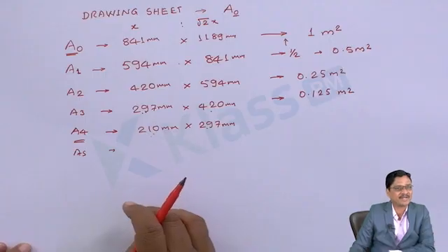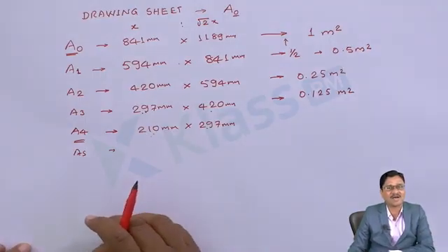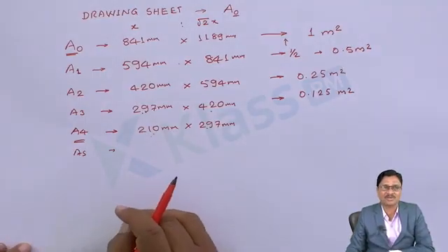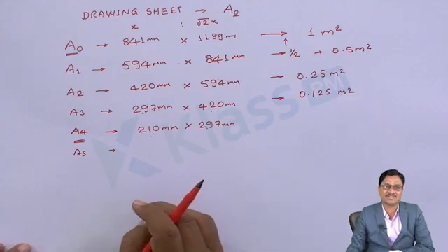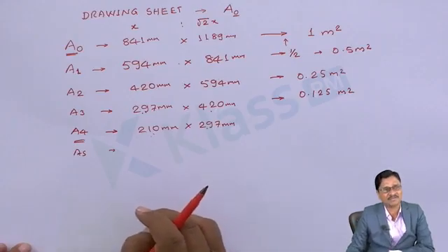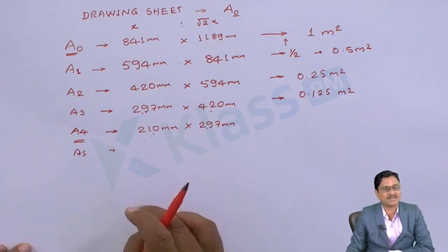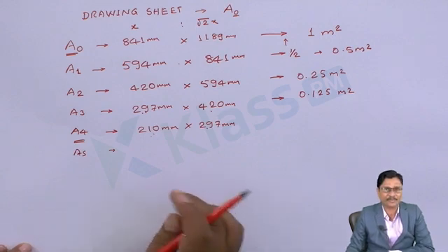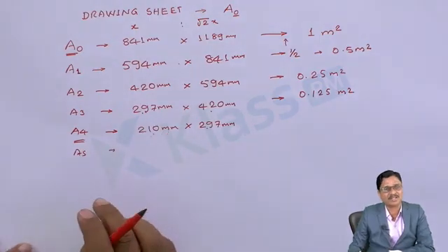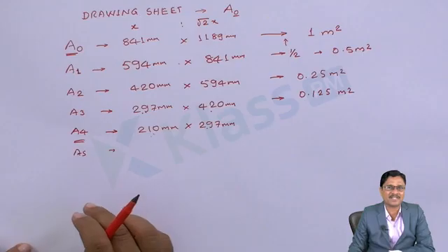In our drawing requirement, A4 is the smaller size and the larger size is A0, which has an area of 1 square meter, with dimensions of 841 mm by 1189 mm. The width to length ratio is 1:√2. So those are the details about the drawing sheet. You have to use a white, tough layered sheet for our drawing work.